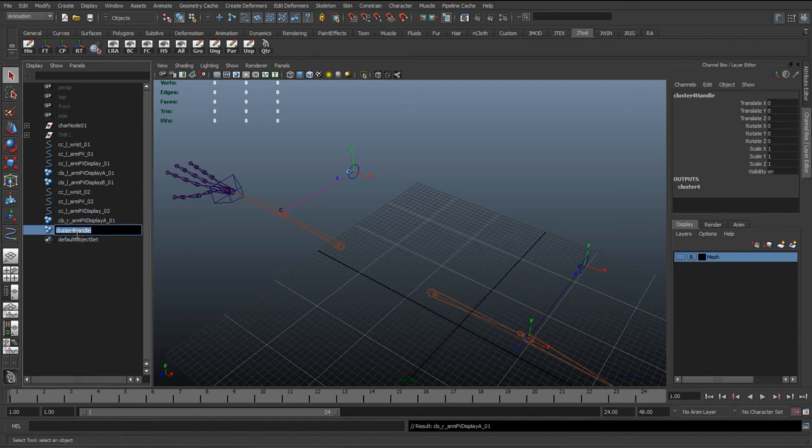And it can be seen as a bit tedious going through all these, renaming them, but this is sort of the boring side of rigging. You've got to go through and make sure it's all named correctly, because later on, if you come back to this rig a few days down the line, or even a few hours, you might see these clusters, and if they're just called cluster 1, 2 and 3, you'll have no idea what they were for, and you'll have to go digging through your rig again just to find out what they were. But just renaming them at the start, we just know what they are. Right, make sure I rename that B.